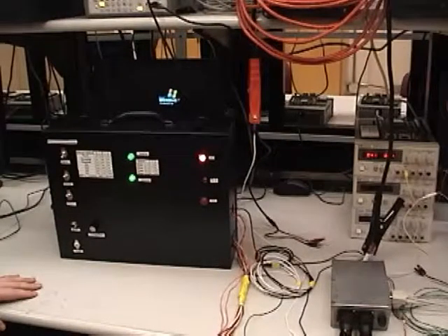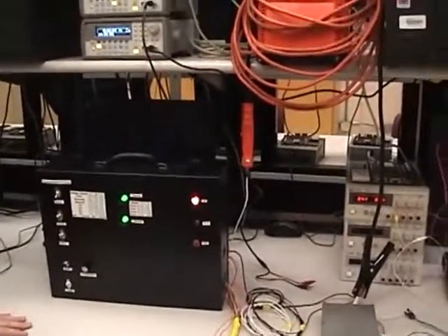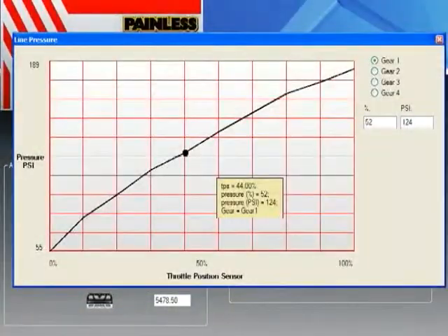The reason that you want a low or high line pressure, and want that to dynamically change, is because you're basing it on where the throttle is at that particular time. So if someone is in a car and they lightly press on the throttle and they're taking off very slowly, then you would want low line pressure so that you don't get a real hard shift and squeal the tires every time you're taking off slow.